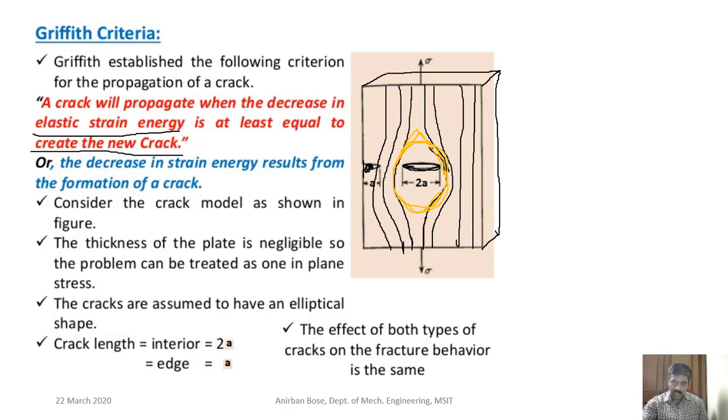In this region there are no stress flow lines. That means there is no strain energy stored in this volume. So if you compare with the material where there is no crack, the material where the crack is present will release some of the strain energy, corresponding to the strain energy in this region.